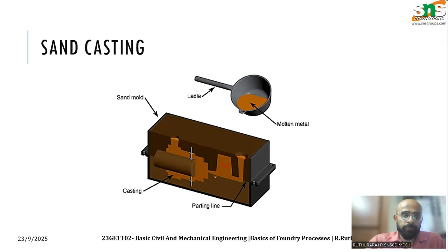Whenever the molten metal is solidifying, it will shrink, because when liquid solidifies into solid, it will always shrink. So it may become smaller than we designed. To prevent that, excess material will be available here. It will get supplied to the mold cavity so that it is completely filled during the solidification process, so that we get a full size casting.